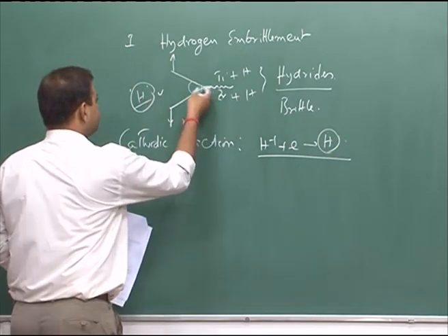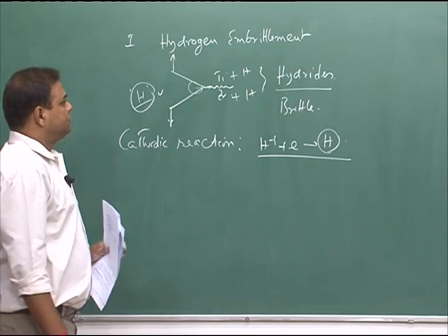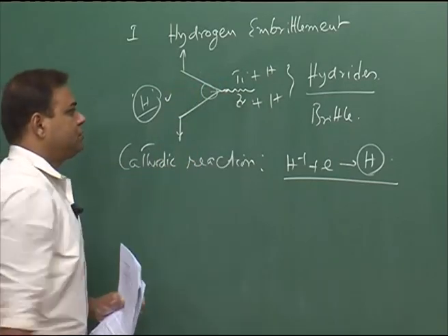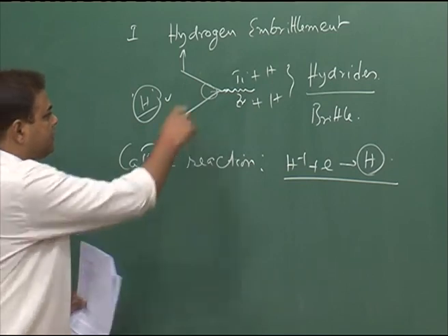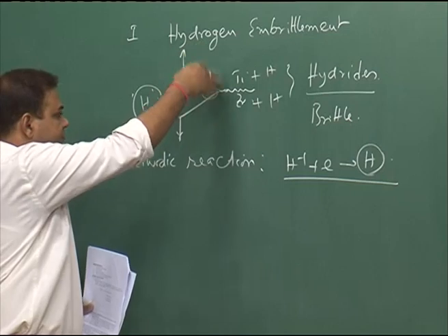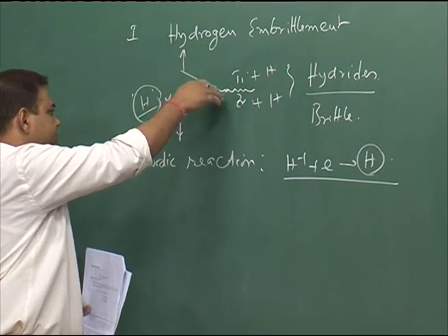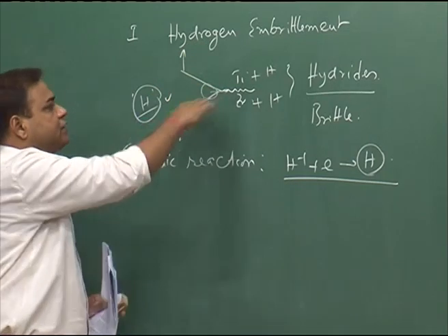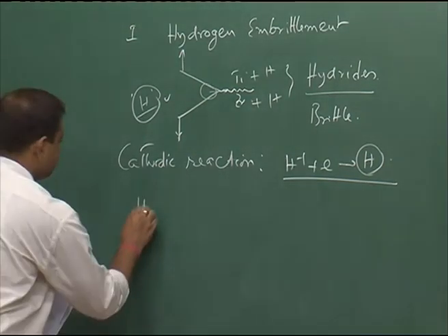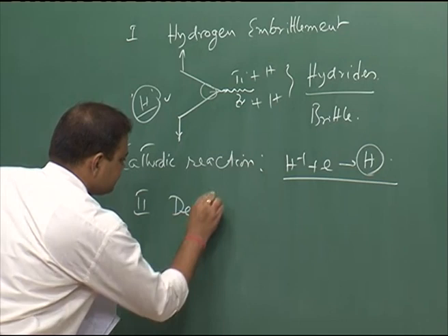This hydrogen can diffuse in and form hydrides with hydride forming elements and make the crack tip zone brittle, and the crack can propagate through that brittle zone. Again it meets the tough matrix, where it is stopped, again hydride forms, and that way the crack propagates. The second stage is basically decohesion.